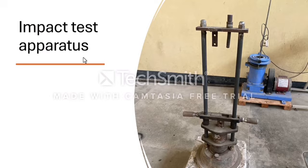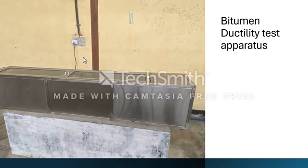Next is the impact test apparatus, which costs around 1,24,500 to 3,32,000 depending on type and features. Its function is to assess the toughness and impact strength of materials, particularly metals. And its principle is that a pendulum or hammer impacts a notched specimen and the energy absorbed during fracture is measured, indicating material toughness.